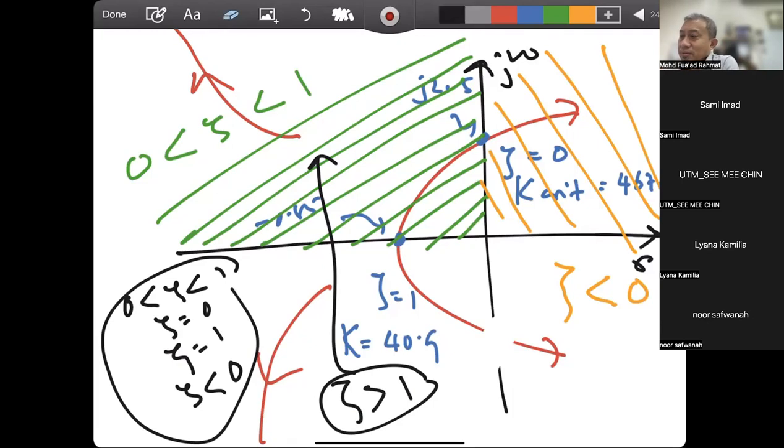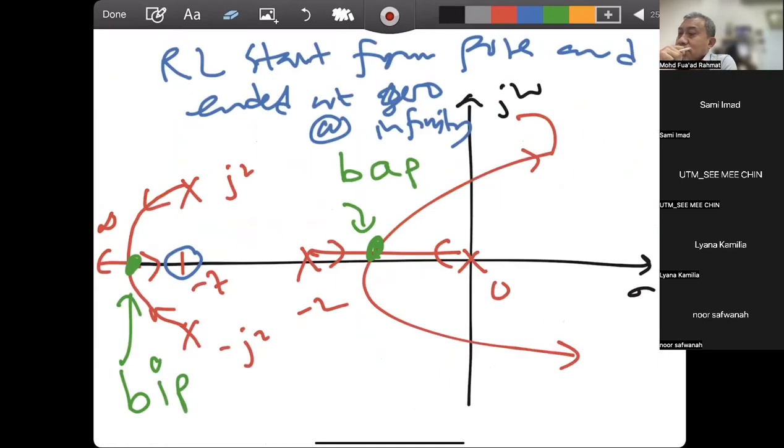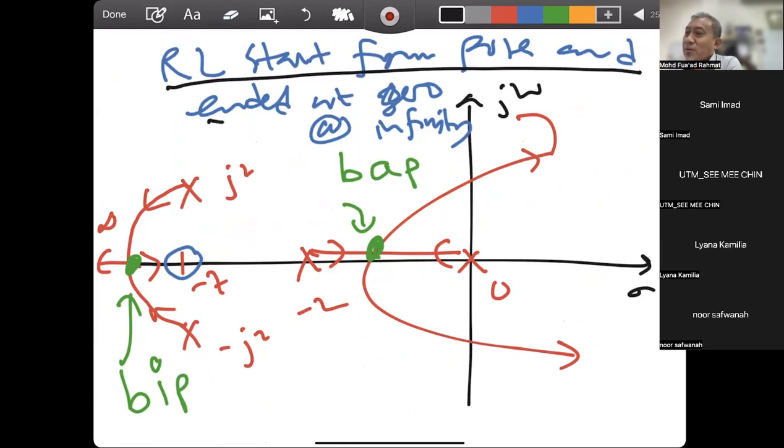Doctor, just one more question before we move on to the next question. When you draw the new root locus, when we added the 0.7, the new zero, how do we know that the shape is concave? Well, it depends on your understanding of this word. Root locus starts from poles and ends at zeros. On the first two poles, there is not much difference when you add zeros at -7, but it really affects when the zeros are near to the poles.